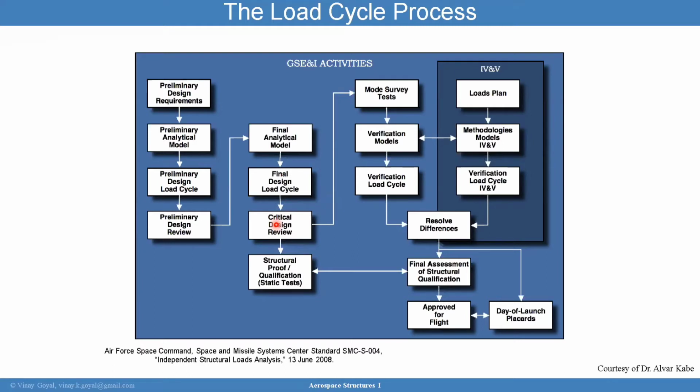But I also don't want a situation with negative margin. If it's negative margin, I have to go back and redesign, which is totally fine, but that's going to affect the dynamic properties again. So when you're in that final load cycle, you want to make sure you're as close as possible to where you need to be. And the hope is that when I run my structure analysis, it is fairly robust to the loading environments I came up with.